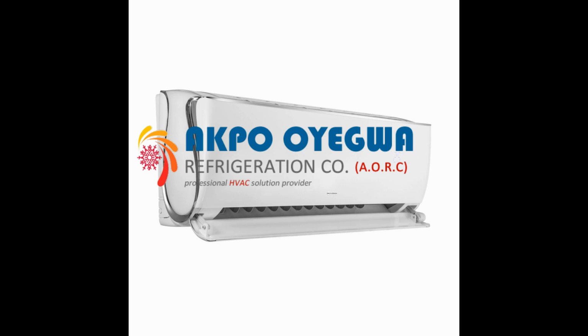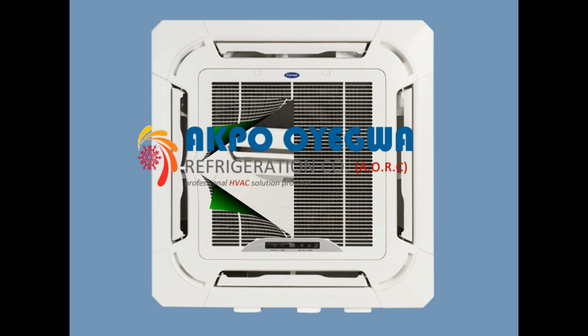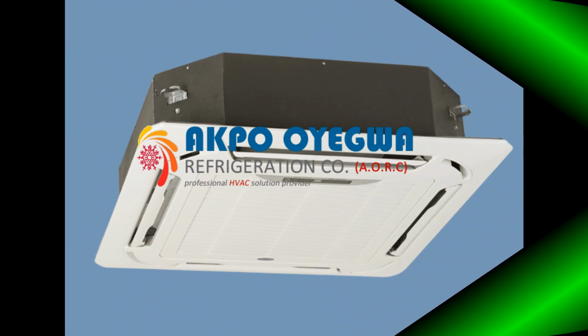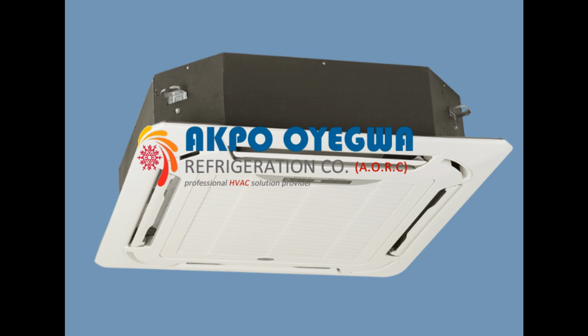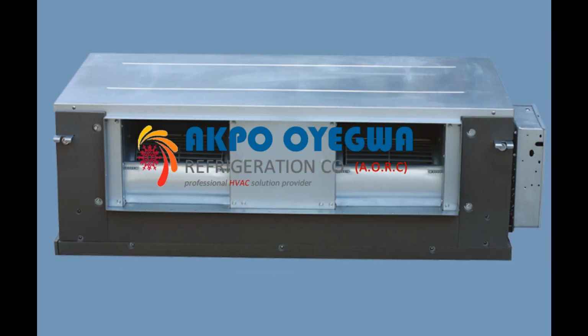5. Ductless mini split air conditioners. These systems consist of an outdoor unit and one or more indoor units that are connected by a small conduit, which houses the refrigerant and power lines. 6. Hybrid air conditioners. These systems combine two or more types of air conditioning technologies, such as an air source heat pump and an electric resistance heater. 7. VRF air conditioners. These systems use a variable speed compressor to adjust the amount of refrigerant flowing to multiple indoor units. 8. Chiller air conditioners. These systems use a refrigeration cycle to cool large buildings, such as hospitals and office buildings.